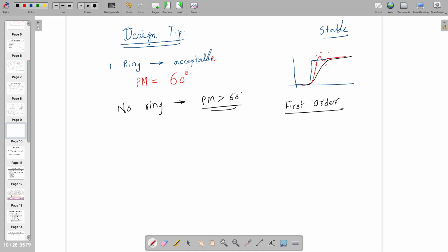This is the experiment I want to do on MATLAB, that if you are writing something like this, have you seen such a system ever in reality? Have you seen such kind of system? No? Okay. Can you find out the transfer function of this circuit? This is V in and this is V out. So what is V out by V in? As I told you, there is an assumption that the capacitor is fully discharged, it has only 0 volt at the beginning, so you can apply Laplace, no problem. So what are you going to get as V out by V in?